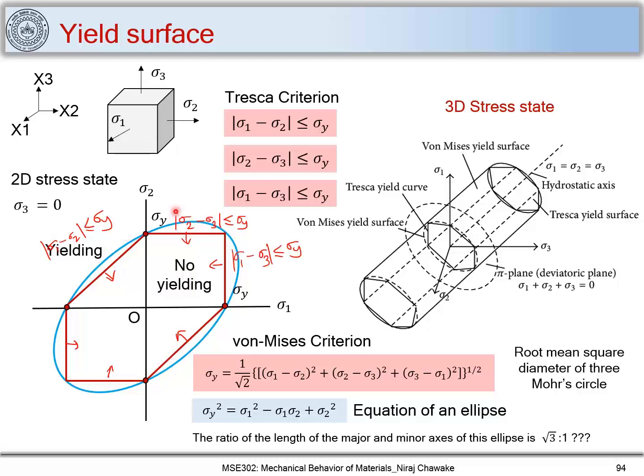So with this, you can understand now, for a given stress state, why we are finding out principal stresses or principal planes, because the ultimate goal was to find out when the material will start to deform plastically. So whatever exercises we did to find out principal stresses using eigenvalues or eigenvectors, and their locations, were to figure out when the material will start yielding. So you can appreciate now why, for a given stress state, we have to find out principal stresses. With this, I will stop here.